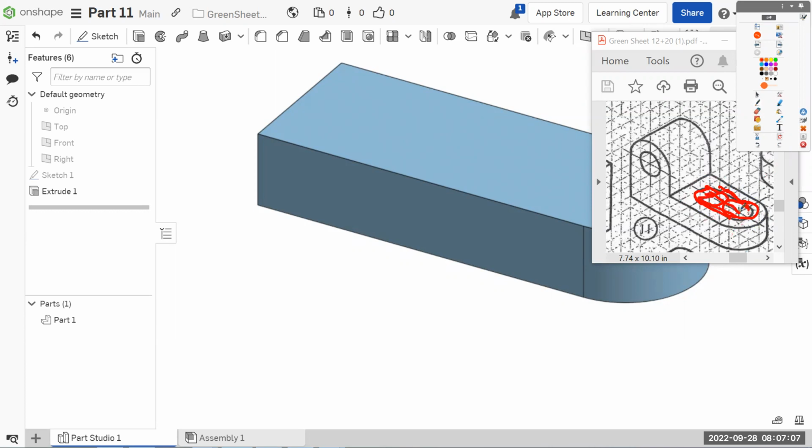However we cover up all of this shape, it doesn't really matter. So we can use this center point, draw a circle with a diameter of 2. Then I'm going to dimension, put another diameter of 2 circle straight over that's separated by 1, 2, 3. Let's just do that first.